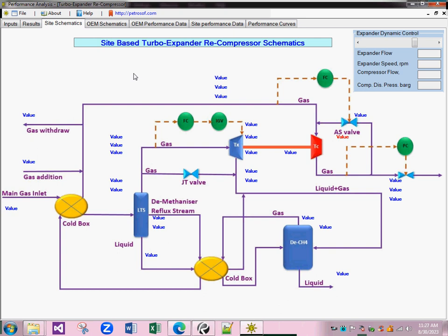And then after the separation of the vapors and liquid stream in the demethanizer column, the resulting vapors leaving the demethanizer column, or the gas stream, pass through various heat exchangers and then go to the suction of the compressor side, where the compressor again adds energy to this low pressure gas to a certain higher pressure and delivers it to the downstream unit. So this is pretty much the very basic high level explanation of the schematics.